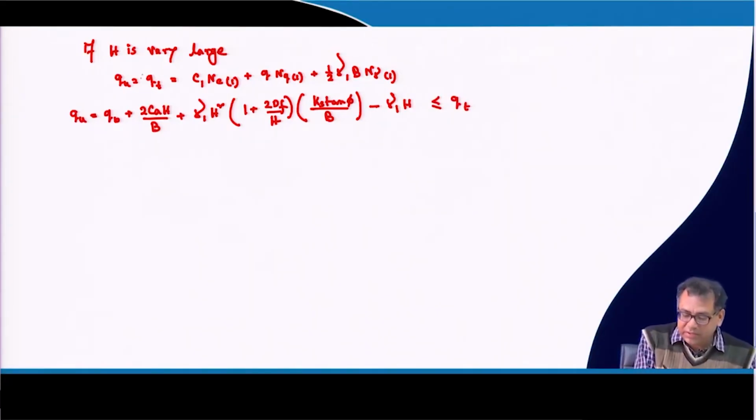Okay. So, qt I will get from this equation, and because this is the limiting value, your qu cannot be greater than qt. It can be equal to qt, and that is the limiting value. It can be either equal to qt or less than that, it cannot be greater than that. So, this is the limit which is placed. Now, this equation is for the strip footing.